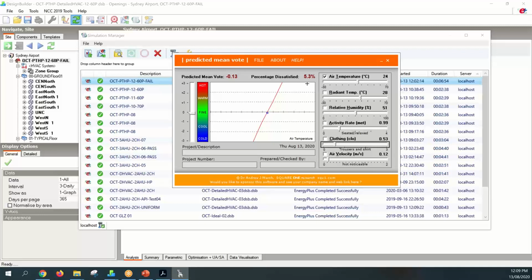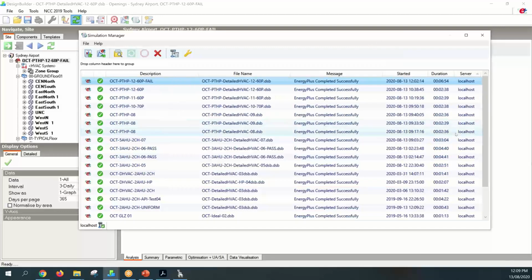Now, by looking at these numbers, one of the definitions of PMV comes out, and that is that when a space is considered to be thermally neutral, about 5% of the people in the space don't particularly like those conditions. That's just the definition of it. You can never get a space that's fully comfortable for everyone. Anyway, I was rambling a little bit there, but I hope that's answered your question, Cynthia.